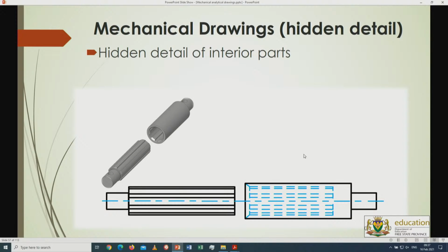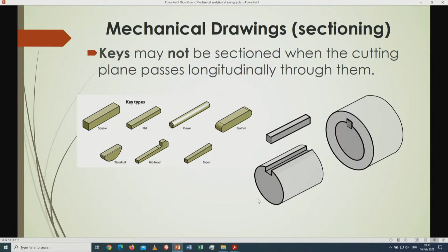Right, so this is a spline. Sometimes it appears that the hidden detail lines can be very close to each other, in some way confusingly close to each other. So this is the case where you have to show all the lines. Luckily it's symmetric, so the front part and the back part look exactly the same, and therefore we don't show the back part as a couple of lines. Of course we have to be accurate in this. You can't just abruptly start drawing some hidden detail lines.